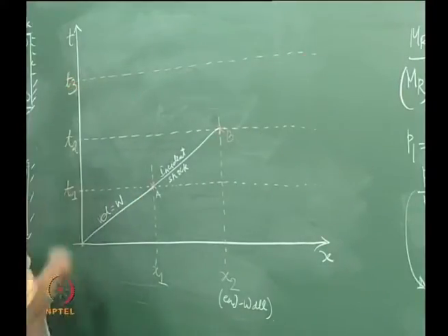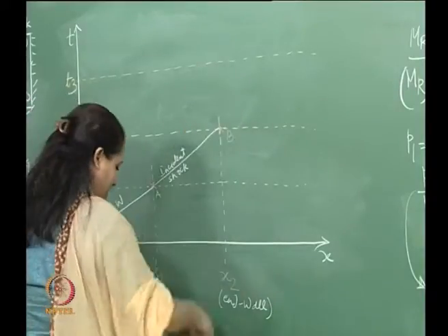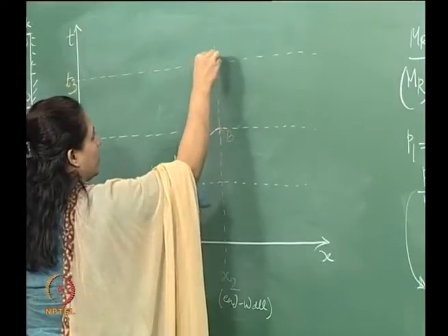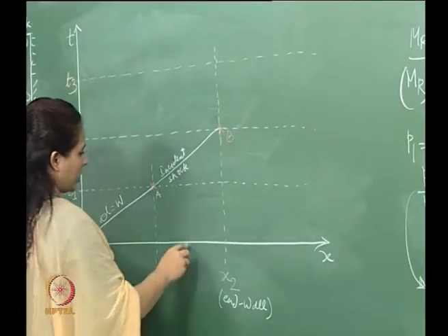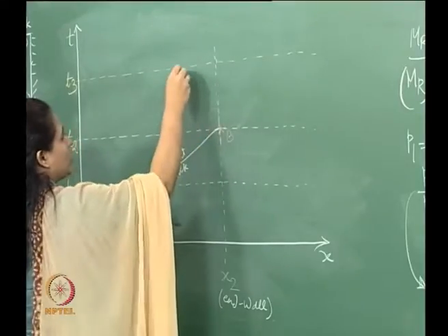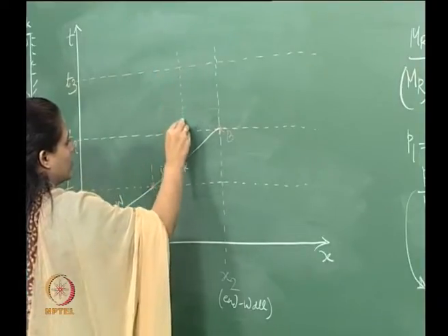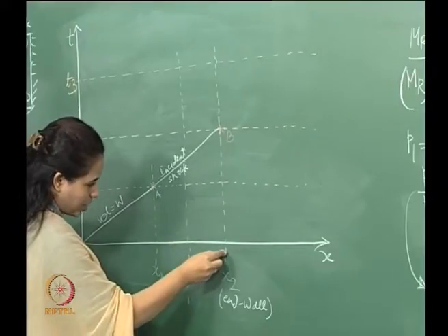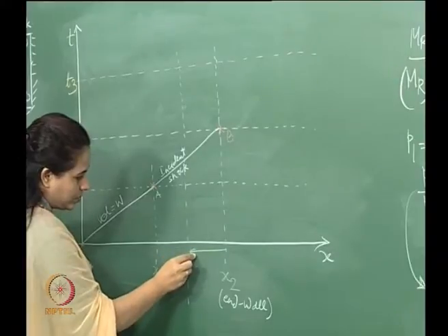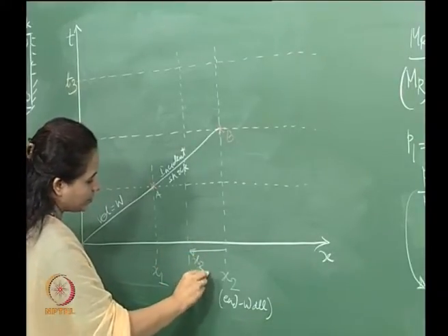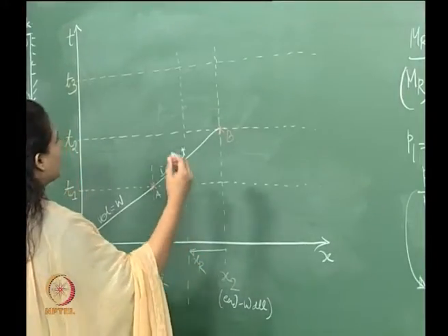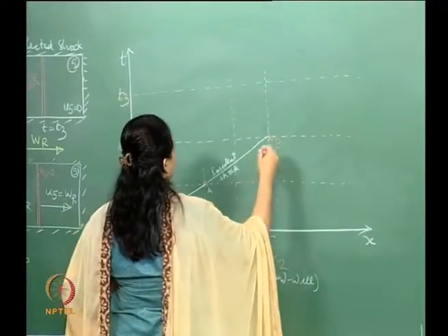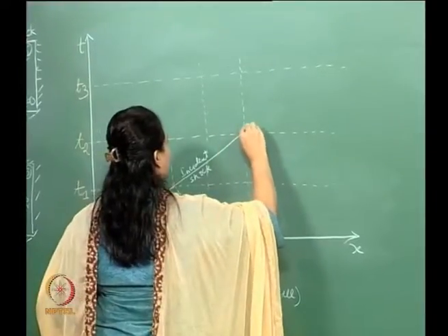so this is t3, okay, and so now the origin of the reflected shock is going to be here, at this point B, right, but the velocity of the reflected shock is going to be different from w. So therefore the slope of that is going to be different. So say it travels by some distance, and say which is here. So essentially it travels from here in the opposite direction like that. Okay. So let us just say it travels by some distance xr, the origin now being here. So therefore I have this reflected shock wave.